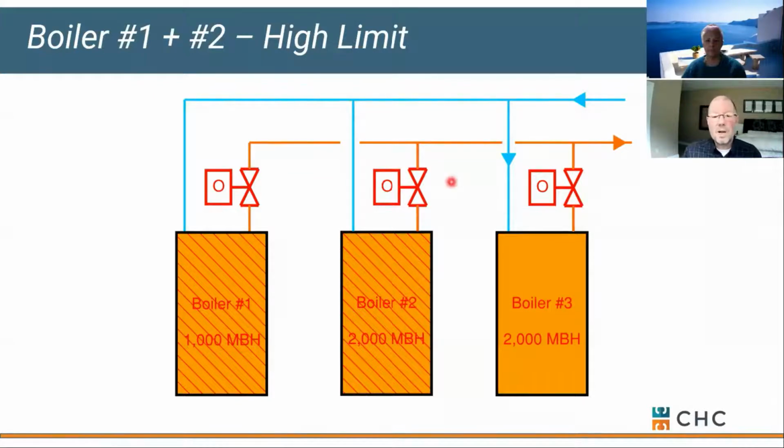How would you propose correcting this boiler layout? Please select all that would be of interest. Make boiler 3 the lead boiler. That is an option, agreed, but every time boiler 1 or 2 was calling for water, there's nothing to force water down here. So that would still be problematic.